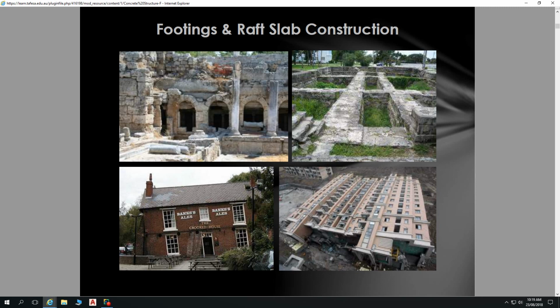A negative side membrane has moisture coming in behind it. In the main, negative side membranes are not as effective as positive side membranes, because moisture tends to affect the bonding. Although when something is impregnated it has a far better bond. But essentially, what you're doing there is a positive side membrane, because it's coming in from the outside.